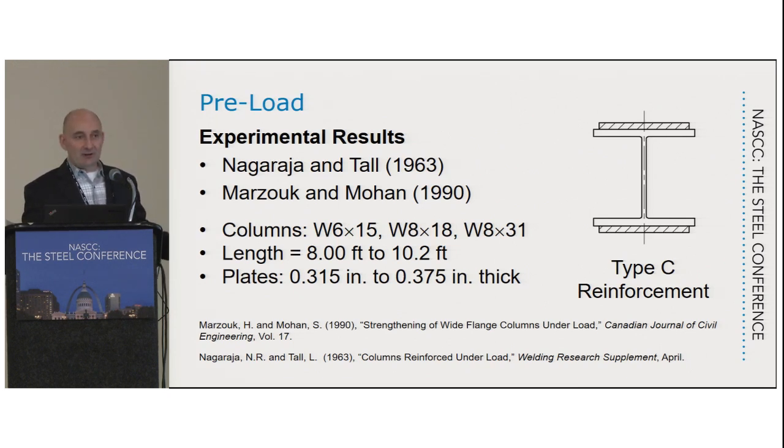It is based on a lot of different shapes, but also it includes a lot of the wide flange shapes with compression residual stresses. Okay, so you add a weld here near the tip of that flange, and a weld causes really, really high tension residual stresses. It doesn't matter what was there before. It kind of totally blows that out of the water and does its own thing. So you end up with compression originally, and that changes to very high tension residual stresses.